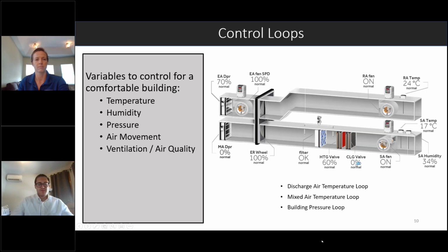That's just pretty much measuring whether or not you have power going to that fan. Another option would be you could put an airflow switch across that fan on either side to actually detect whether or not there's air being sent through. So it's determining pressure on either side of that fan.